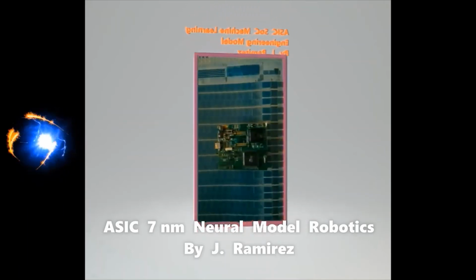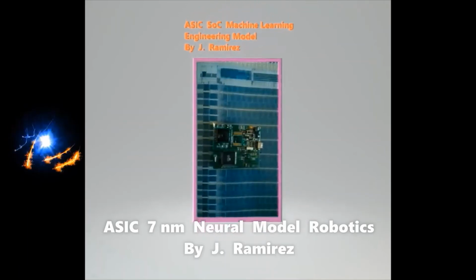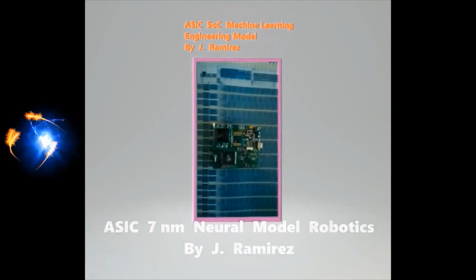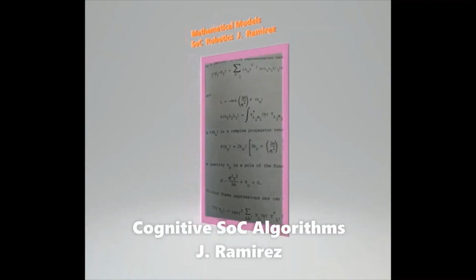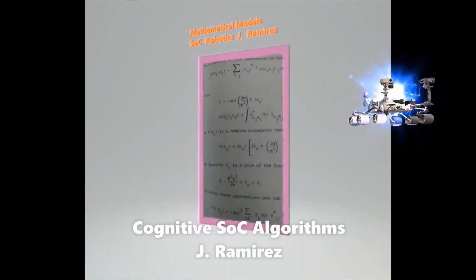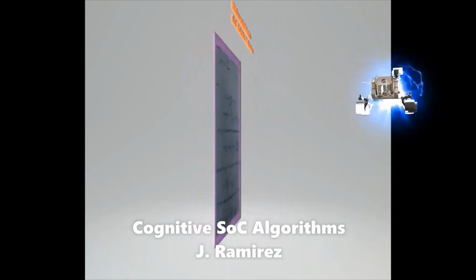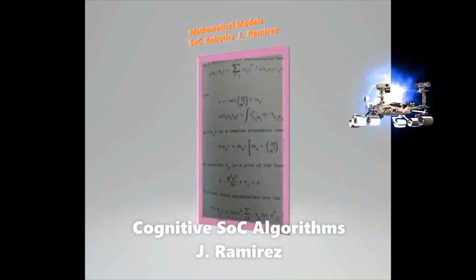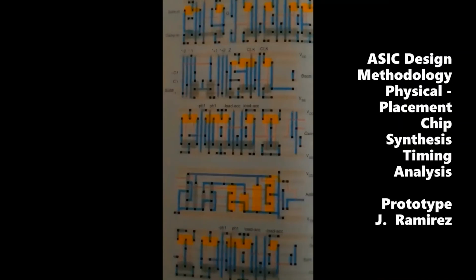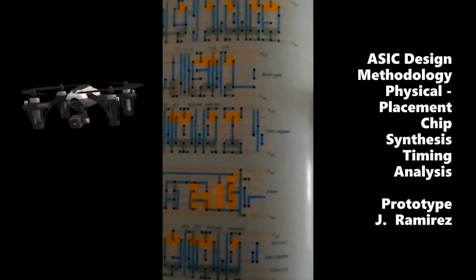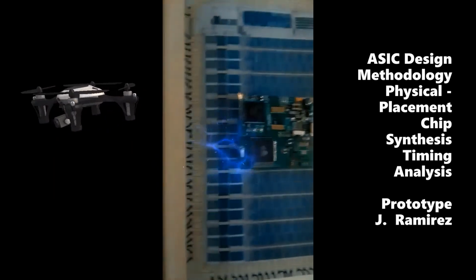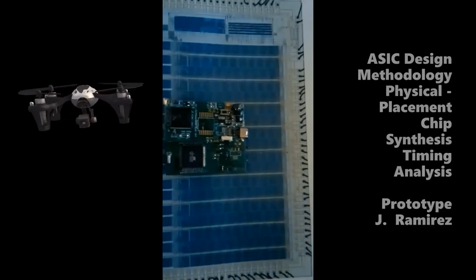The hierarchical timing closure methodology for this design was performed starting with the logical hierarchy, carrying out manually or automatically repartitioning the design to obtain the physical hierarchy. 1. Perform quick floor planning and placement of the hierarchy. It provides a better starting point for timing planning. 2.